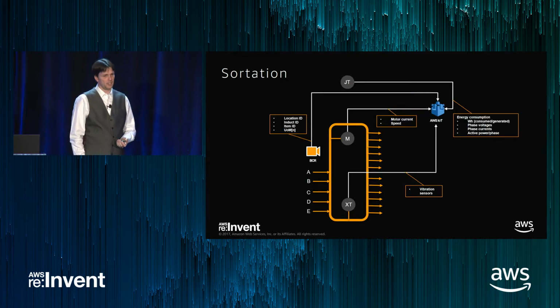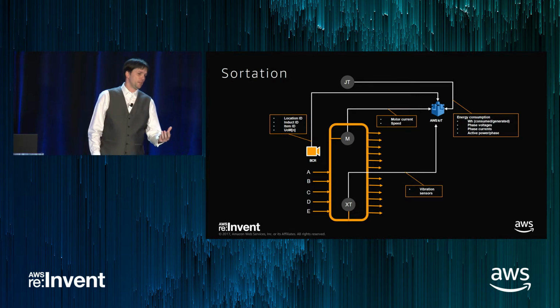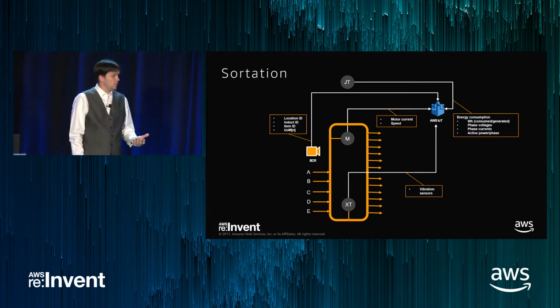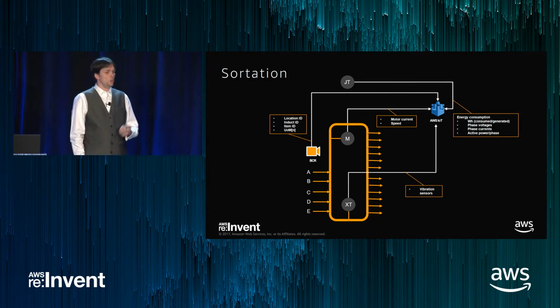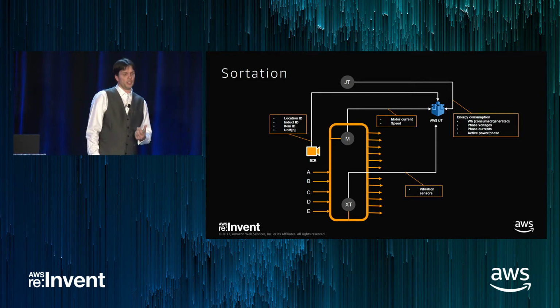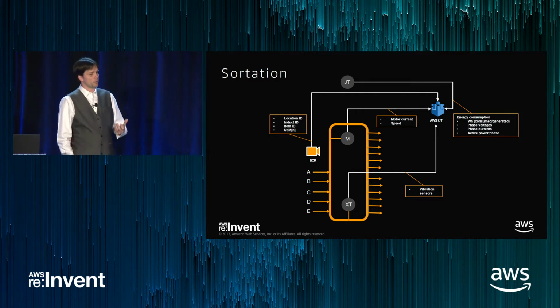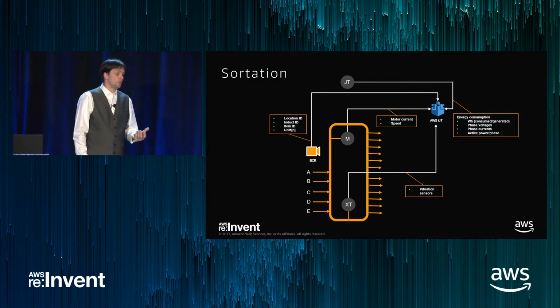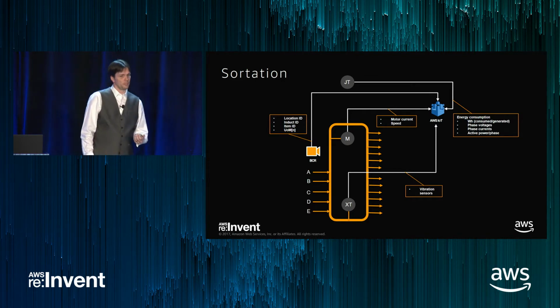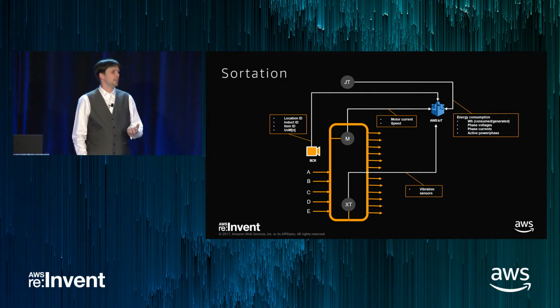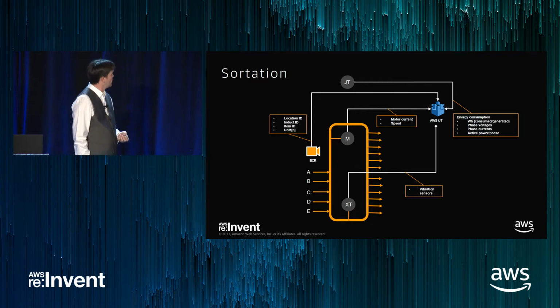Looking at a diagram of it, you've got your loop sorter. We're measuring with the barcode readers, again, the read rate. So how many packages is it reading correctly? Do we need to increase there? We've got power consumption that we're measuring. We've got data coming from the motor, motor currents, the speeds, but also vibration monitoring. So we need to start looking at how are we loading the sorter, and is that affecting the vibration? Is that affecting the current that the motor is drawing? So all of this, we're trying to now push into AWS, and that data, the analytics, that's where Dario is going to pick it up.